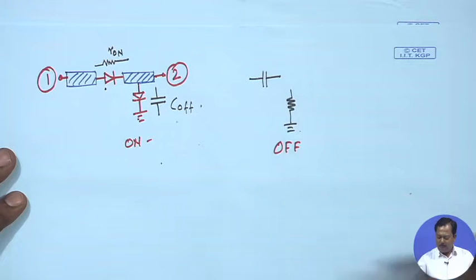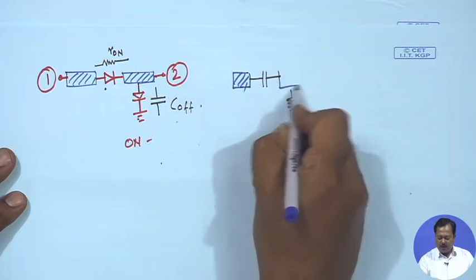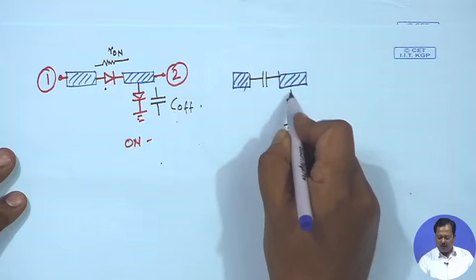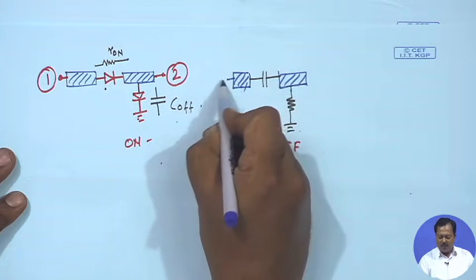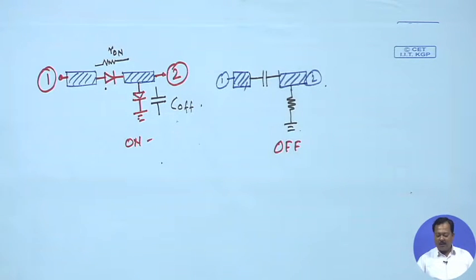So, we have isolation due to the first diode and further isolation from the second diode. That is how we can improve isolation here, but insertion loss will degrade. But anyway, for any practical applications, we mainly look at the difference between the insertion loss and isolation.